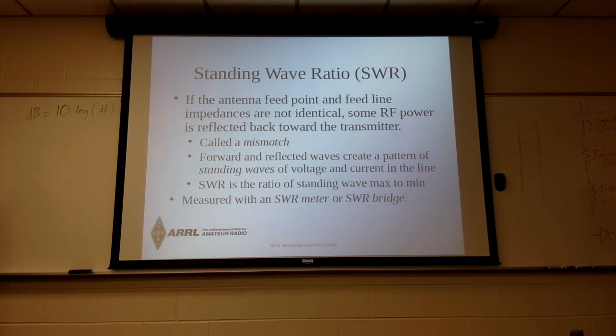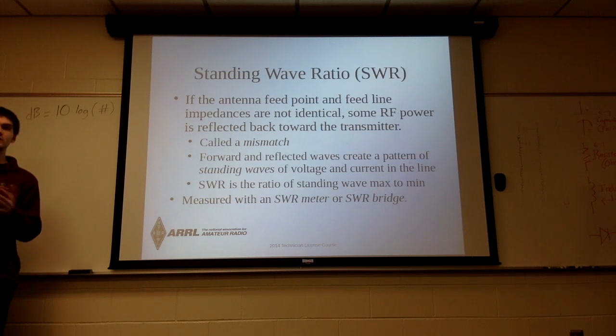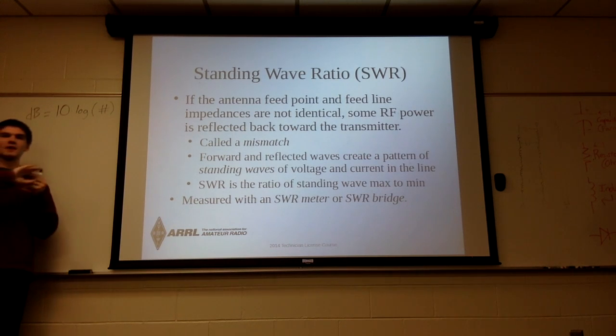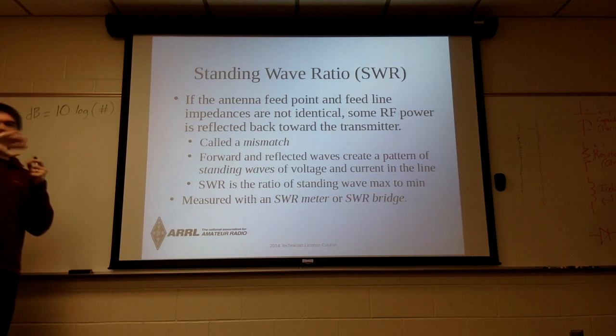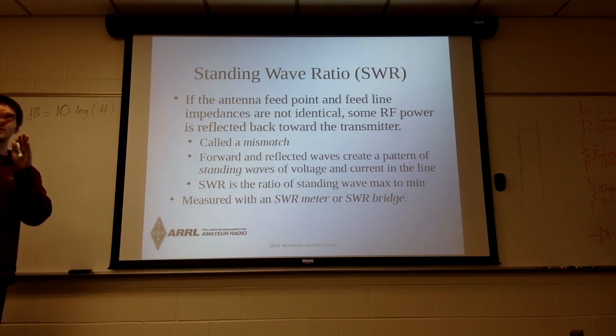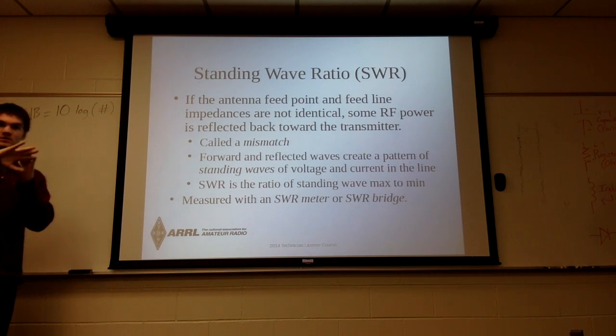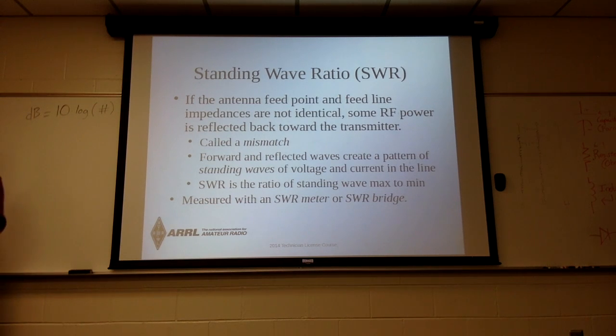So it's important that the feed line you're using is matched to the radio that you're using. If it's not, once you send out a radio wave and it hits the feed line, some of that power is going to be reflected back into your radio, which is very bad. Ideally, you would have no power reflected. That would be if they were matched perfectly. But we can measure that level of reflection by something called the standing wave ratio.